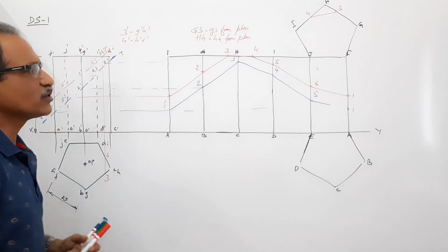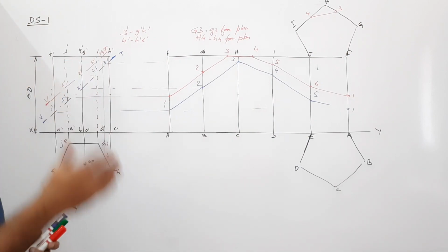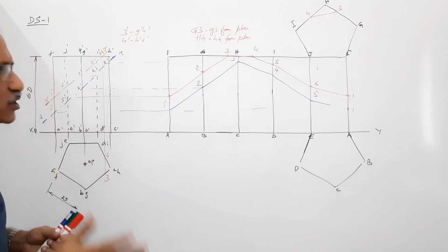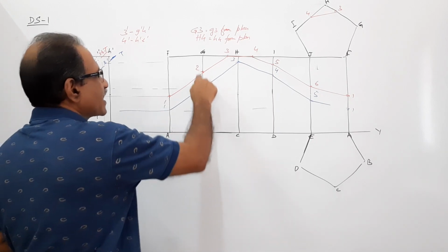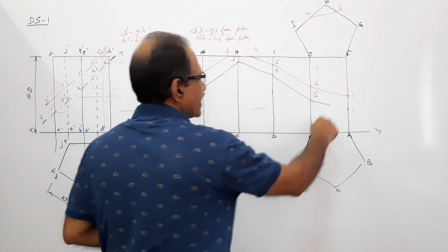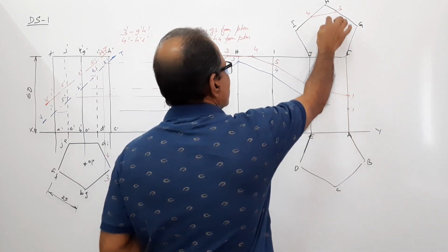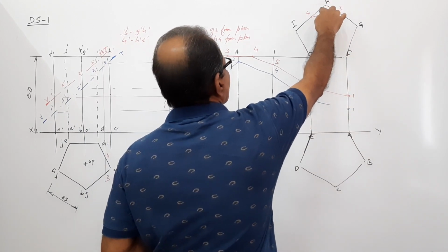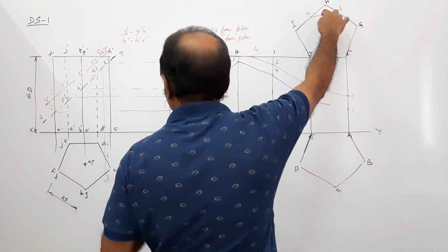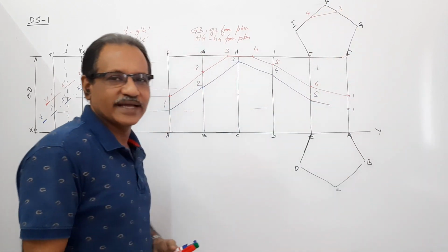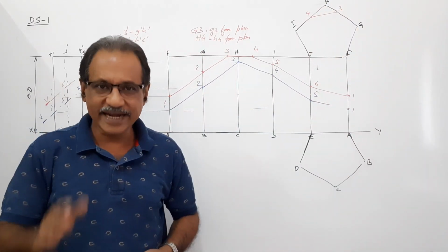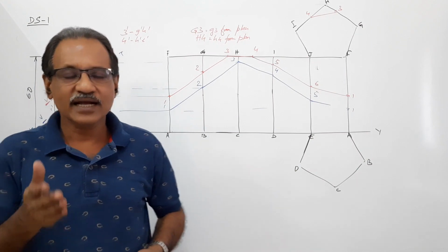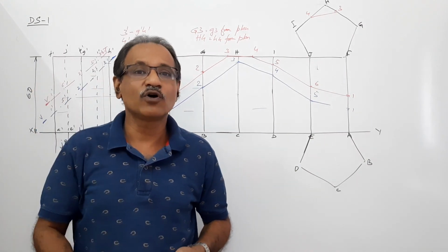Now, you have to darken the portion below the cutting plane and keep the other portion light. So, you have to darken these lines. Agreed? This pentagon also, this small piece of the pentagon you have to darken because that is kept. The other things you have to keep light. This is the third cutting plane, where the cutting plane cuts the top of the prism.